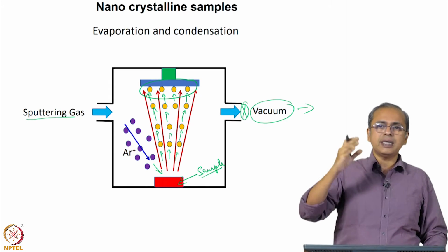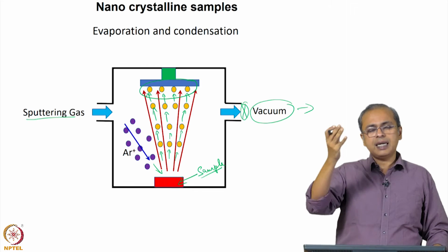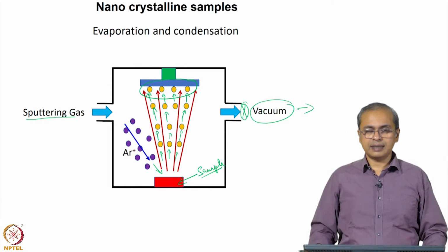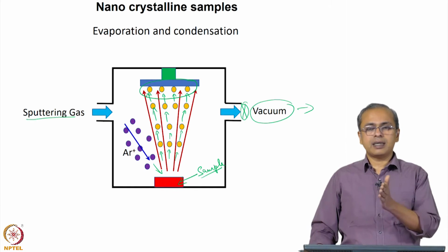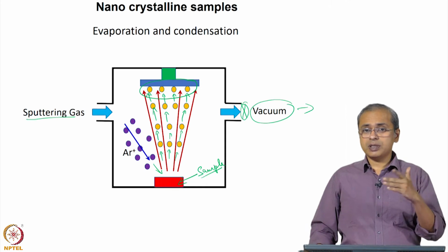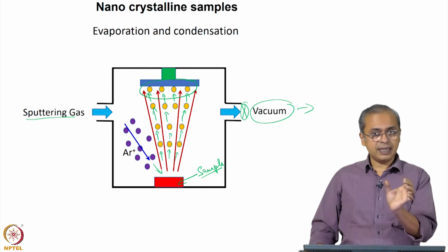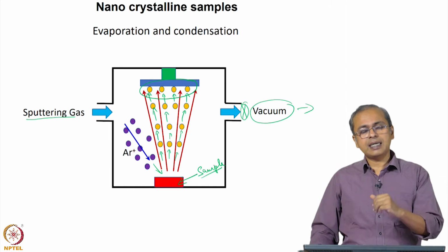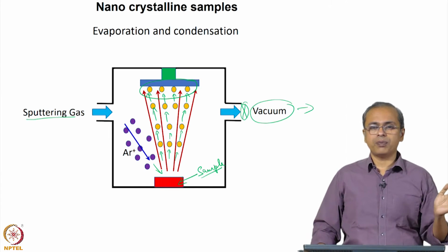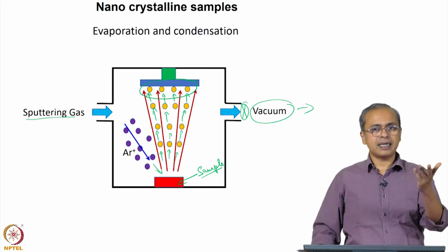It is gradually removing material, and that material eventually ends up on the substrate that you are condensing. So, it takes some time based on how much sample you want to evaporate. In the thermal evaporation process, the boat remains intact, and whatever sample you put inside almost instantaneously evaporates. If you put a few grams, all of that is in vapor form immediately, and it condenses.